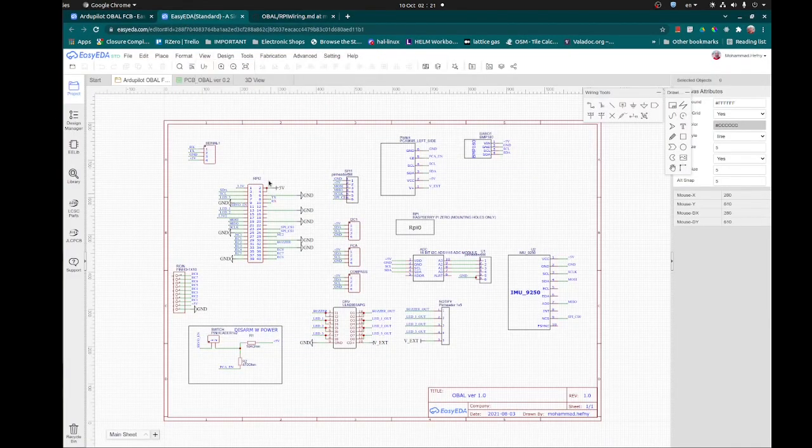First, we have a Raspberry Pi board. This Raspberry Pi has IMU 9250. This IMU has a gyrometer, accelerometer, and magnetometer. It actually has an MPU 6050 and a magnetometer. And it is connected via SPI. Then we have a barometer BMP 180, and it is connected via I2C.